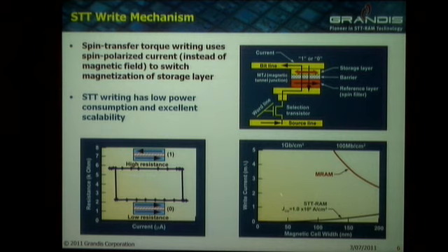And then I think the key difference compared with a conventional MRAM cell is the scalability. If you look at conventional MRAM, which was a very hot topic a few years ago, and there were some MRAM cells in commercial production these days up to about 16 megabits. But the problem is when you scale MRAM below about 100 nanometers, the current you need in order to switch the cells, to create enough magnetic field, rises quite fast. And essentially, it's not scalable below about 100 nanometers or so. Whereas with STT-RAM, the write current you need in order to switch the cells reduces as you reduce the cell size. It's proportional essentially to the area.